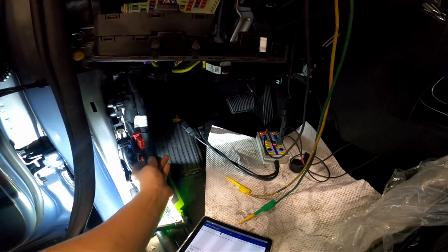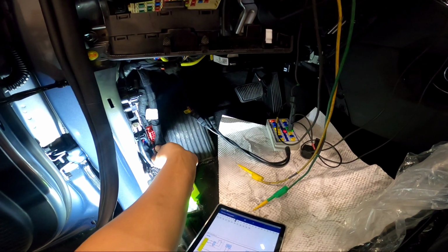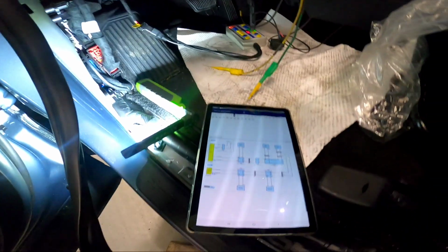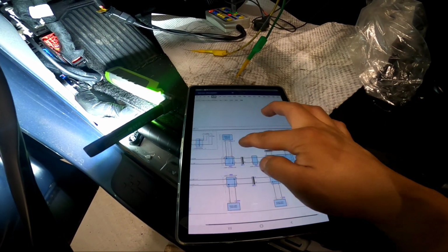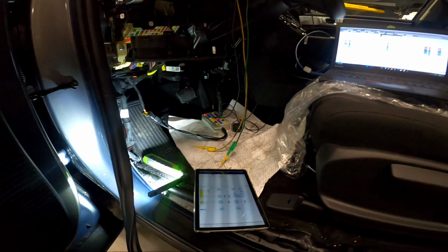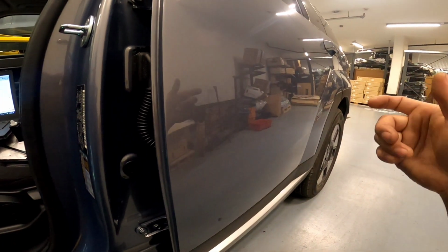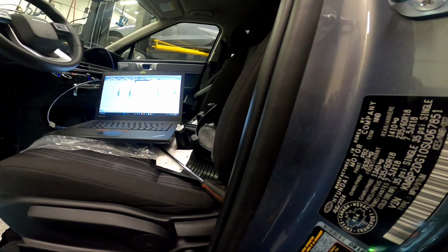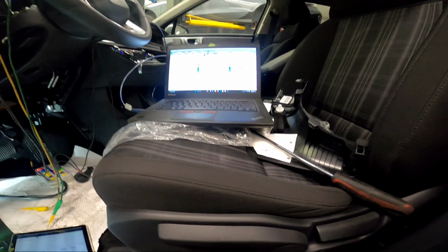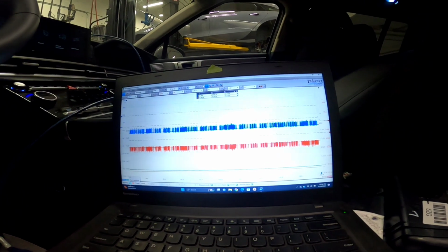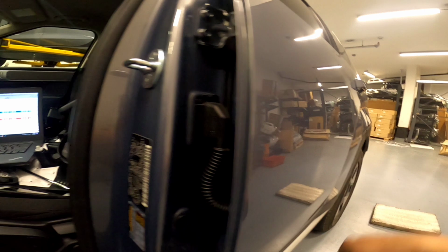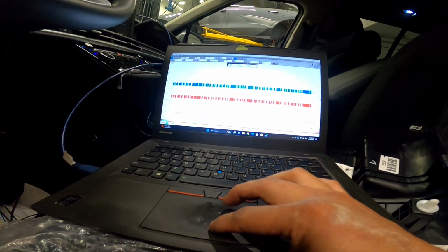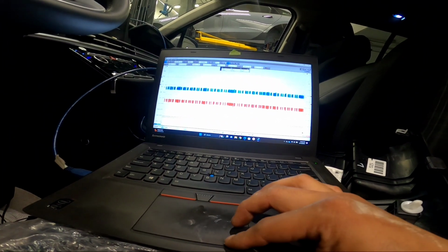So no choice, we're going to start unplugging stuff and see which one in this area. Front view camera, rear corner, front AC control module. Let me check underneath the vehicle in that area, and see if I can unplug that stuff and watch our voltage waveform. Okay, so after I unplugged the FR51 on the left rear corner, our waveform went back, which is a very good thing.